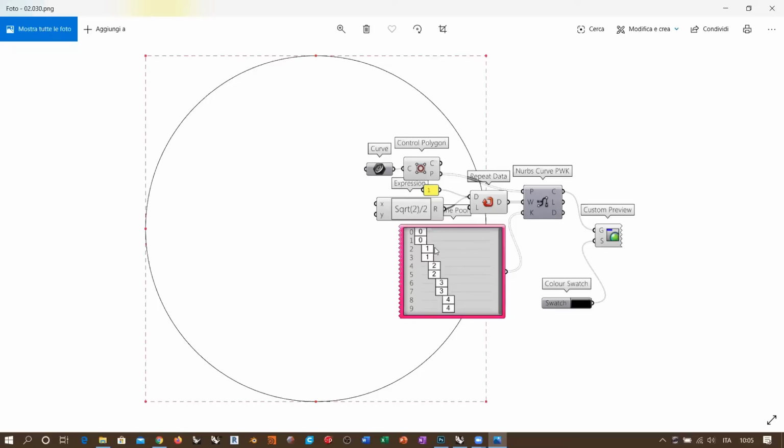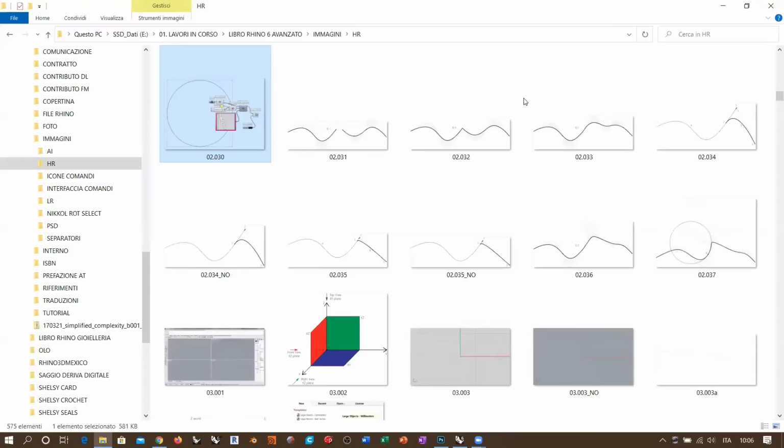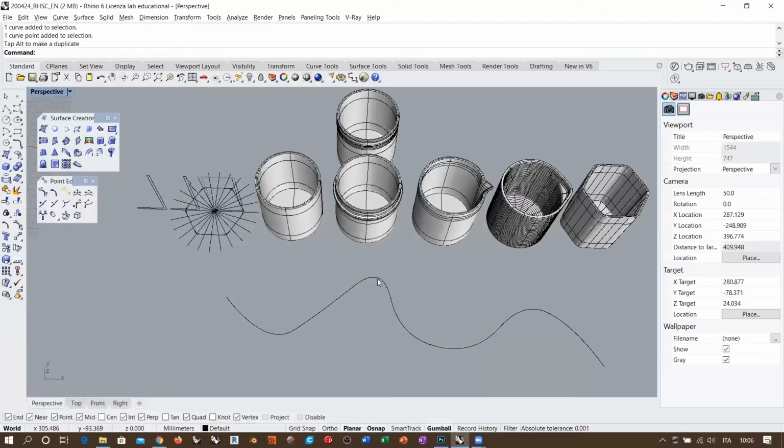And in this case, as this is a degree 2 curve with kinks along the path, because these are full multiplicity internal knots, then whatever type of deformation you do with the control points, you will have some vertex appearing. But this is a very particular case, okay? It's not like a general rule, as you can see here, for example.